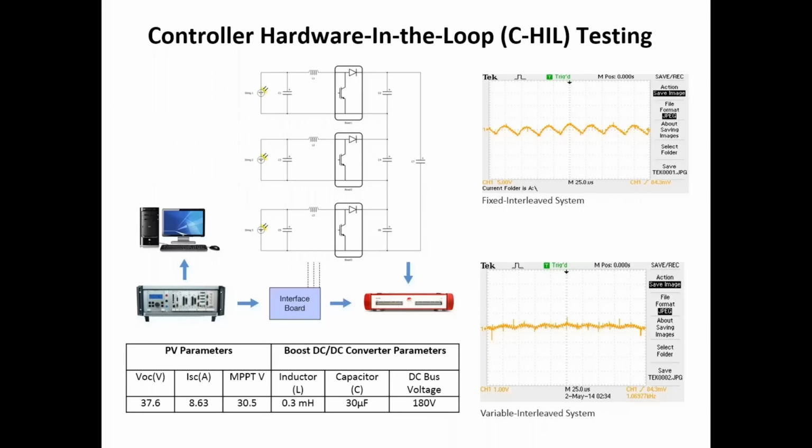At that time, we were using Texas Instruments DSPs, and we physically built DSP cards which could run simple buck converters, boost converters, and resonant converters in real time. And real time at that time was 5 kilohertz PWM, 10 kilohertz PWM at the max. That was the limit with the DSPs that we had.